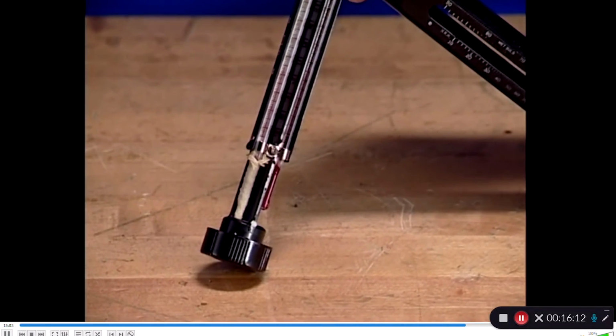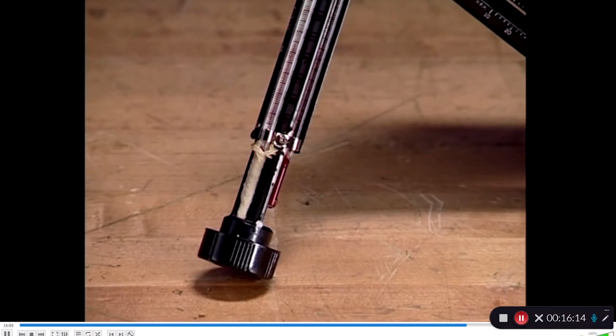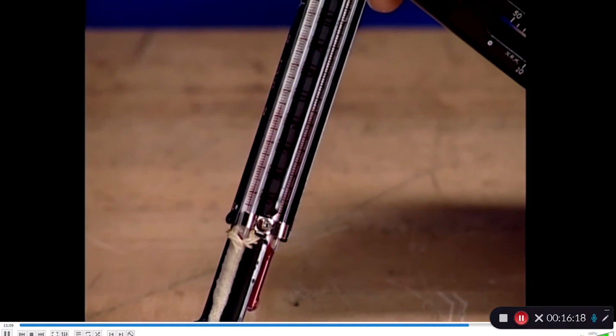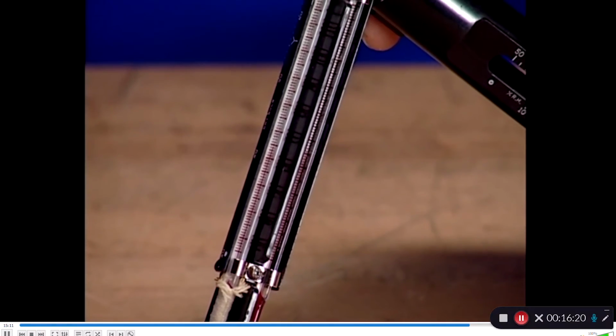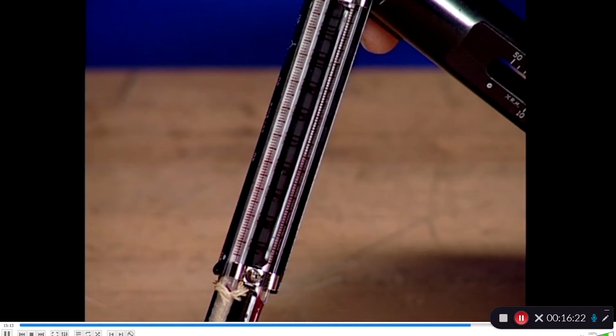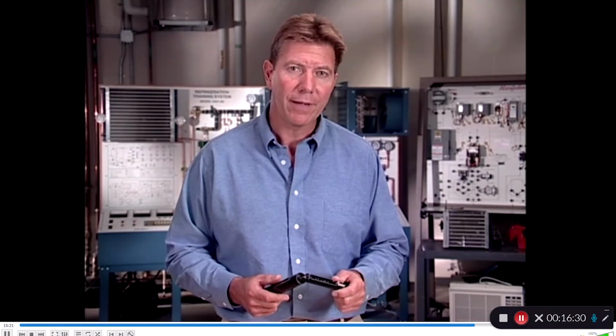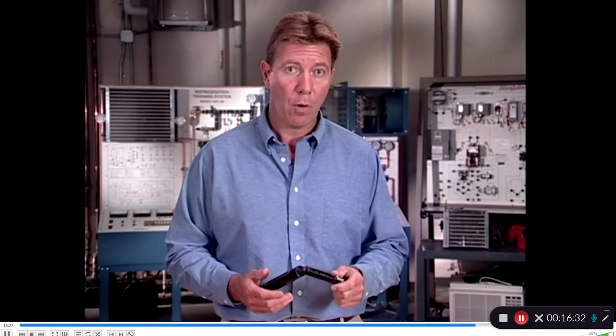If the air surrounding the wick is very dry, the moisture from the wick will evaporate. As the water evaporates, it absorbs heat, causing the temperature reading on this thermometer to be lower than the temperature on the dry bulb thermometer. Drier air will cause more water to evaporate, resulting in a lower wet bulb temperature reading, while very humid air will result in a wet bulb temperature that is very close to the dry bulb temperature reading.